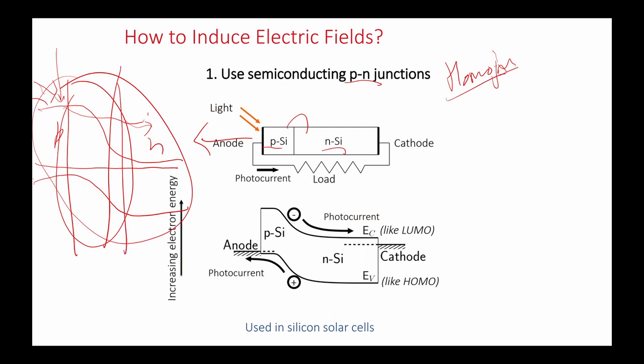If the electron hole pair is generated in this region, because of the electric field in this region, which is a built-in electric field, there is a gradient in the conduction band and the valence band, which is due to the Fermi level being constant throughout the PN junction semiconductor.